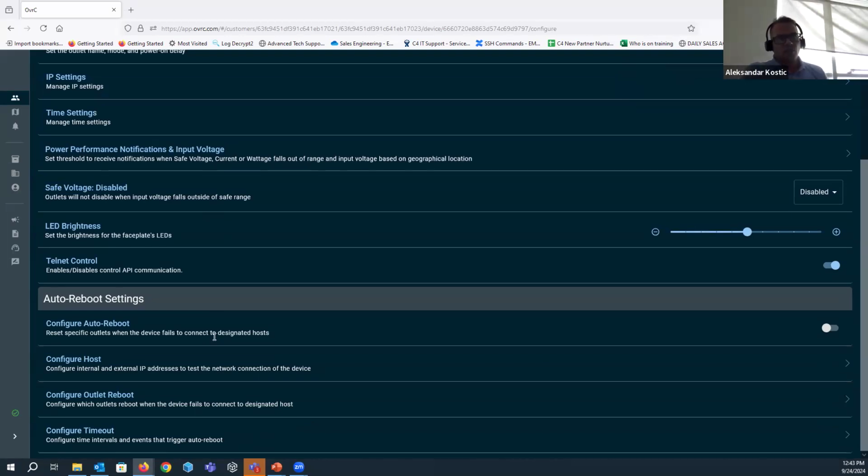And the third, the most advanced way of power outlet control is auto reboot. Auto reboot, in fact, provides the possibility that your WattBox itself knows when to reboot a certain device, and typically it is most commonly used with the router. If the router drops the internet connection, WattBox can be configured to ping some public IP addresses, some Google or Yahoo or whatever. And if this ping drops, it will restart the router and that way try to get your site back online.